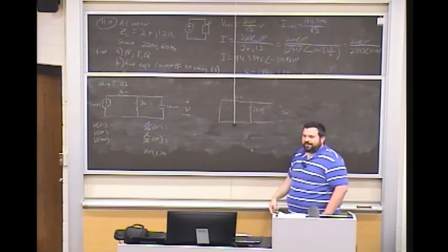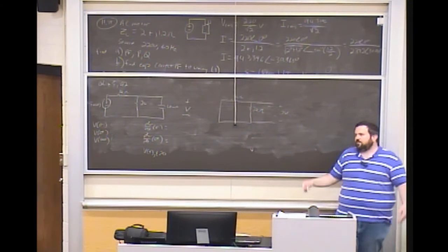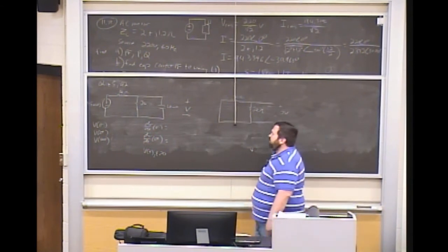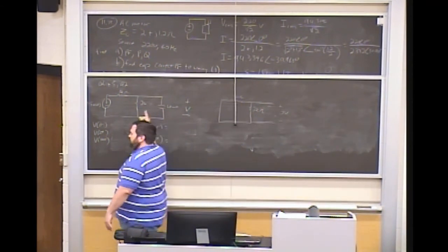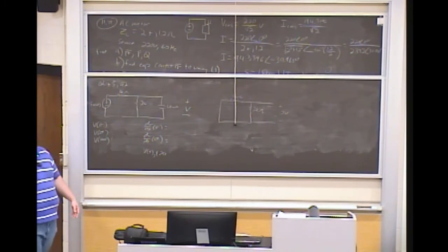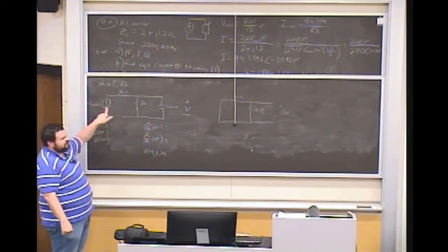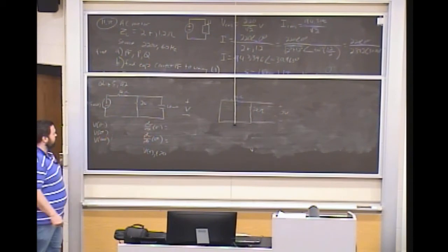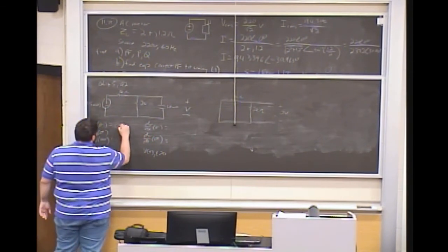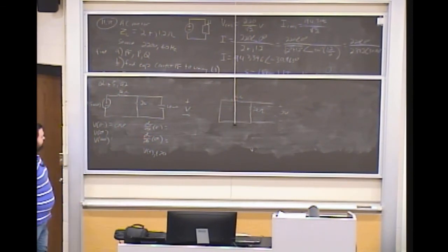There's no supply. Nothing's on. So effectively, we would assume this has behaved like a source-free parallel RC circuit. And over time, any charge on the capacitor has had enough time just to dissipate. So our V at 0 minus is 0 volts.